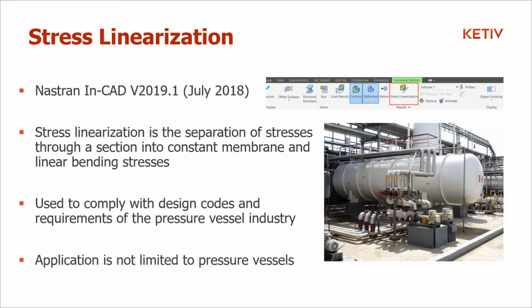It's also worth remembering that while the lion's share of the application is for pressure vessels, it's not limited to pressure vessels. In fact, you can linearize stresses through any structure as long as it makes sense to do so, by which I mean as long as it makes sense to extract separate bending and membrane stresses.